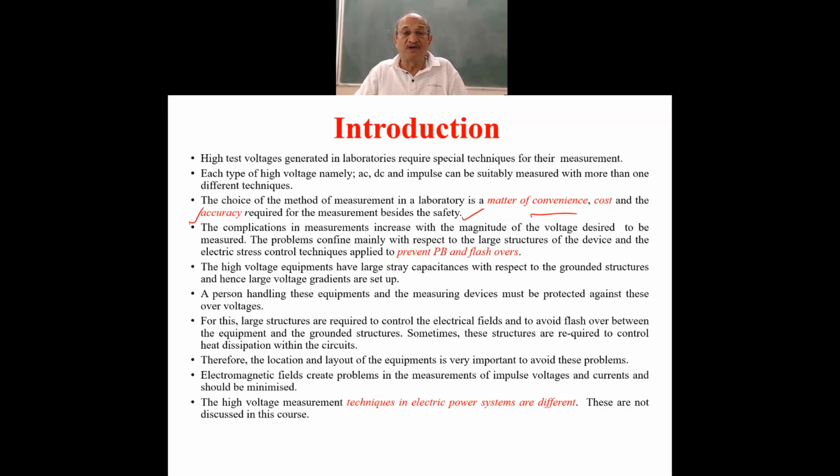To bring down the high field intensity when you are using the connection for high voltage, you have to increase the size of the metallic connector with which you are connecting.